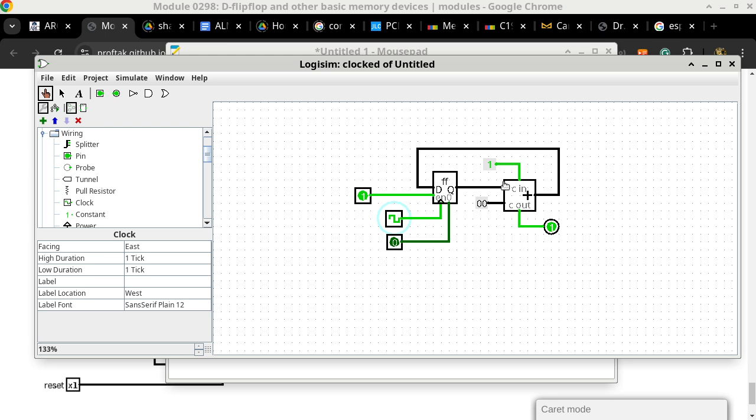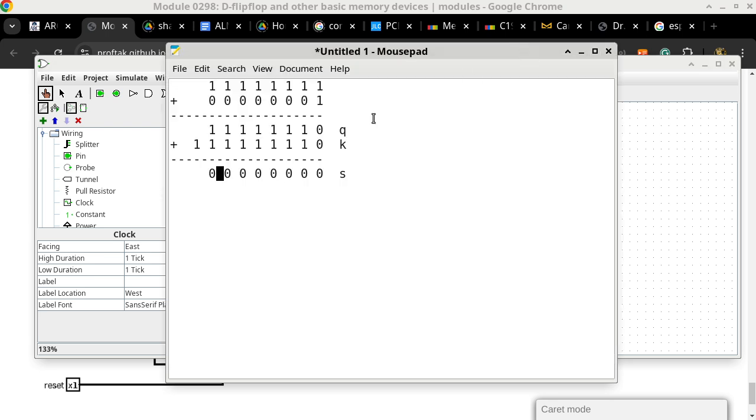So I did lie a little bit. I wasn't exactly accurate, because in this particular example, y should be all zeros. It is k0 that is a 1. If I want to reflect the actual circuit, this is what's happening. But it still ends up having the same result, because in this case q would be a 1, and 1 plus 1 would still be a 0 contributing to this one over here. So it will still end up with exactly the same bits, but this better matches the circuit that we saw earlier than the previous example.